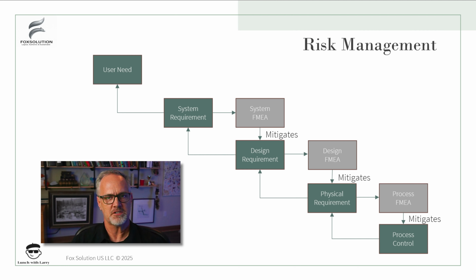The same thing in the physical requirement. So if we have a design requirement that is maybe something like in a sterile barrier bag, the design requirement is the sterile barrier won't migrate harmful bacteria. And some of the physical requirements might be you want to use Tyvek, or you might have a 3/8 inch bag seal. And those are critical dimensions and/or characteristics of the design that are necessary to assure that that bag doesn't migrate the harmful bacteria. So in the design FMEA, we're going through from a mechanical design standpoint now, because we know what component that requirement is deployed in. I can go through and define everything that's required to be in the design to give me that migration remediation.